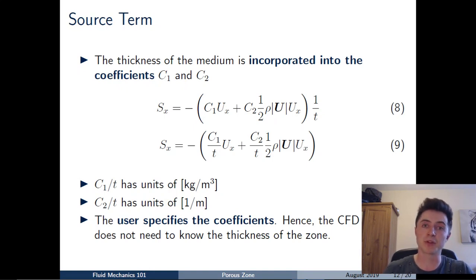Now, before we carry on, it's worth pausing for a moment to be very careful and consider the units of these coefficients before we start deriving them. Now, looking at those two terms there, the second term, remember, with C2 takes the form of a dynamic head, which is a half rho u squared, and that means C2 would have no units. It would be dimensionless.